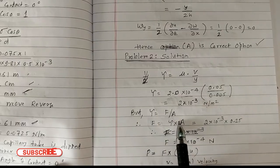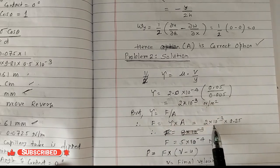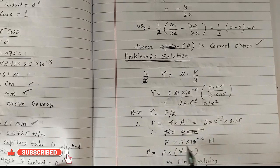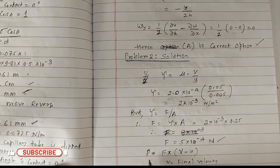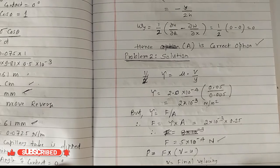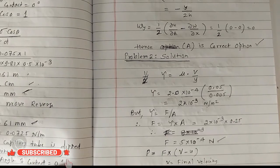But tau is equal to F upon A, force upon area. So F is equal to tau into area, that is equal to 2 into 10 raised to minus 3 into 0.25. So therefore F is equal to 5 into 10 raised to minus 4 Newton. So this is the force. Then power is equal to force into final velocity minus initial velocity. Final velocity is given here, that is 0.05 meter per second, and initial velocity is 0. So P is equal to force, 5 into 10 raised to minus 4, into 0.05 minus 0, which is equal to power is equal to 2.5 into 10 raised to minus 5.